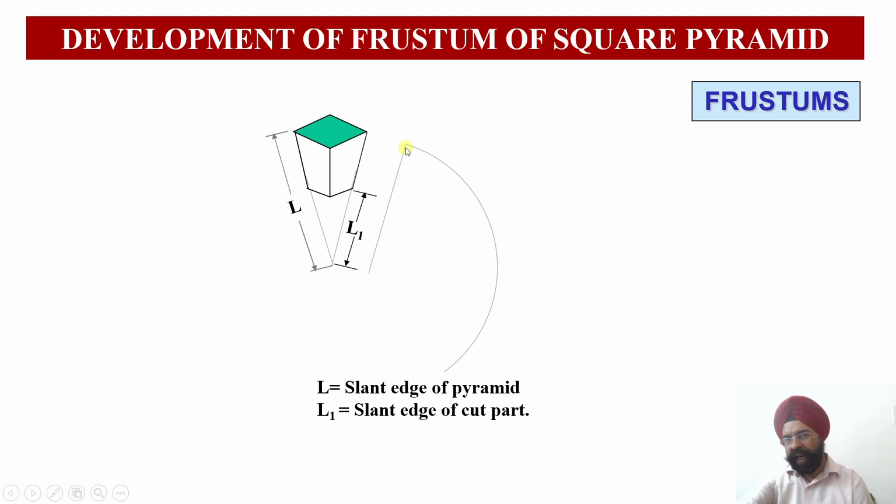So now you see, I am going to draw an arc regarding the full length, and then I'll be drawing this radius over here, and then whatever is the edge length, true length over here, I'll be making 4 cuts. So 4 edges I have to show. Edge 1, edge 2, edge 3, edge 4. So 4 edges I have drawn. Now I am going to join each one of them so that the isosceles triangles can be joined.